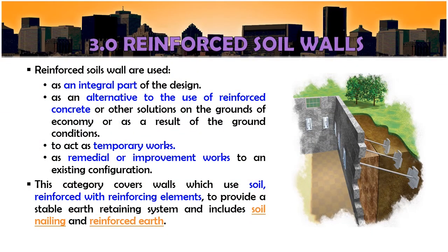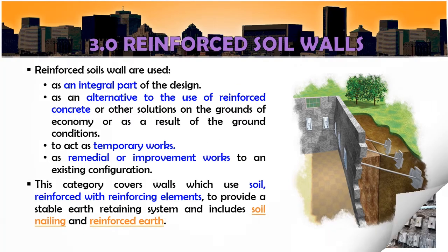Reinforced soil walls are used as an integral part of the design, as an alternative to the use of reinforced concrete or other solution on the ground of economy or as a result of the ground conditions. It also can be used for temporary works and as remedial or improvement works to an existing configuration. This category covers walls which use soil reinforced with reinforcement elements to provide a stable earth retaining system and include soil nailing and reinforced earth.